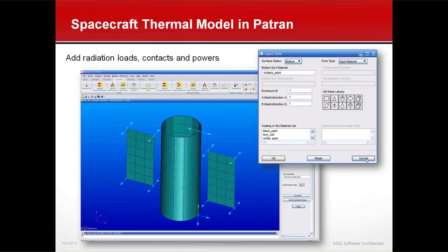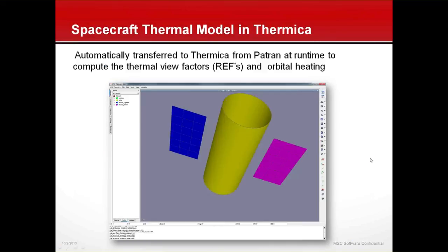That allows you to bring in CAD and mesh things finely and have then larger parts, either group elements together with our radiation super element concept, or use primitives, and keep the radiation model simpler than a conduction model, because radiation view factors go up exponentially sometimes with the number of surfaces. So you really want to try to keep the surfaces down to 10, 20,000 surfaces, depending on if you're talking about detailed payloads and internal things or external things. But externally, usually it's in the thousands typically to get good response. Otherwise, you're sitting there waiting for the software for a long time.